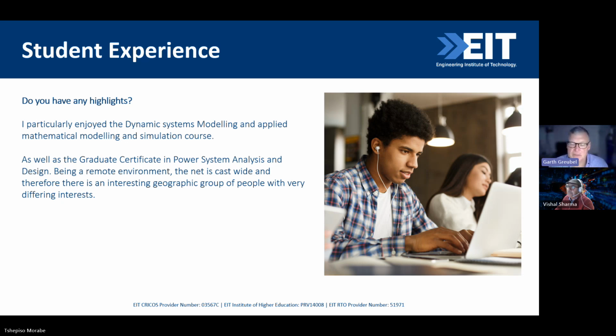So what I'm trying to do is for a client with multiple facilities across the country, so many points of connection, and this particular case study I'm working on is an industrial customer. So they have cogeneration, they've got some embedded solar, they've got some diesel generators as well. And they've got interesting aspects to the load because it's quite sophisticated. So there's some opportunity for demand side management, for load curtailment, and also they have certain loads that are flexible, so you can move it around. You don't have to incur the load now, you can incur it later or earlier in the day.